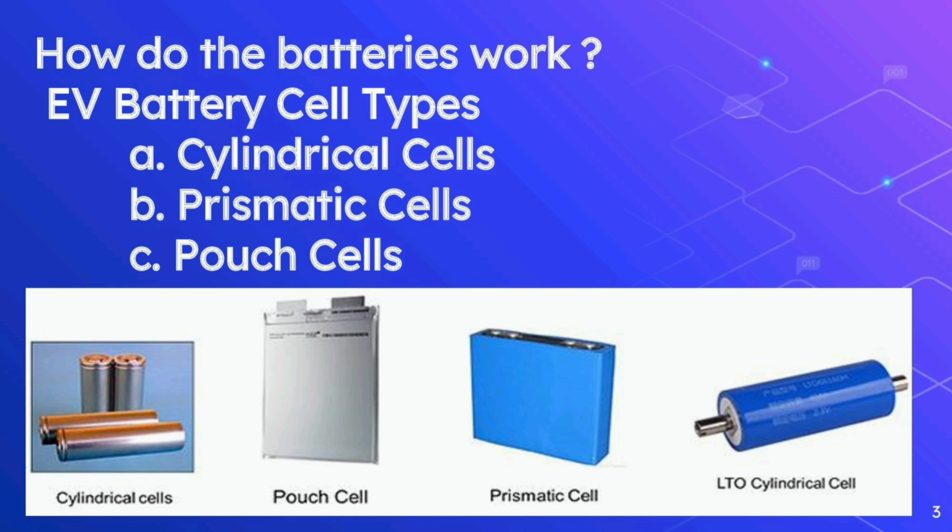So coming to what the cylindrical cells are. Cylindrical cells are the least expensive format to manufacture because they are already self-contained in a casing that offers good mechanical resistance. The technology is not only cost efficient but it is also mature, making the format easy to manufacture. Because of their shape, cylindrical cells have limitations in terms of power. For this reason, electric vehicles with smaller batteries, such as hybrid vehicles, use pouch or prismatic cells to deliver more power during accelerations.